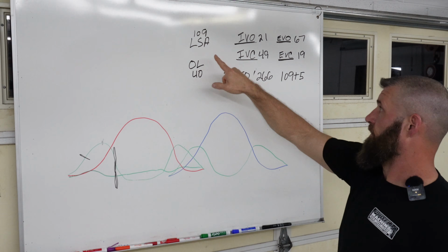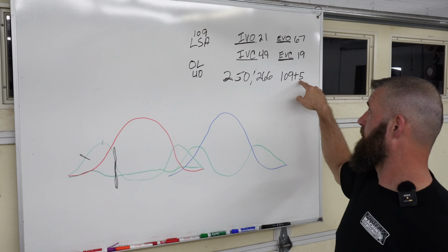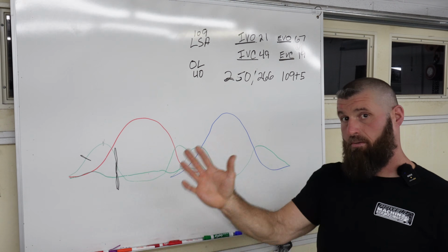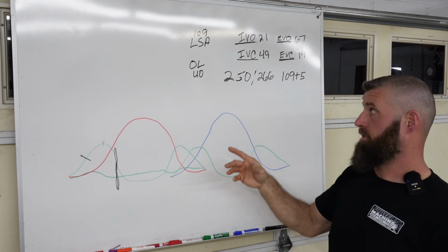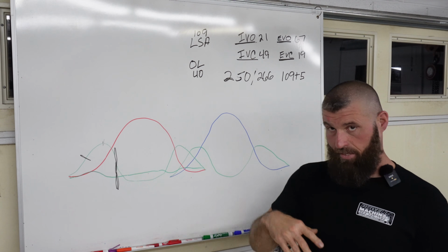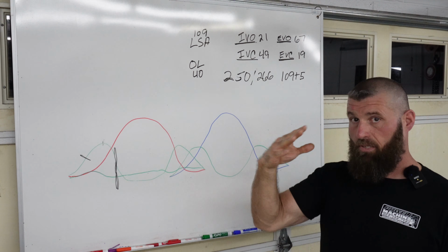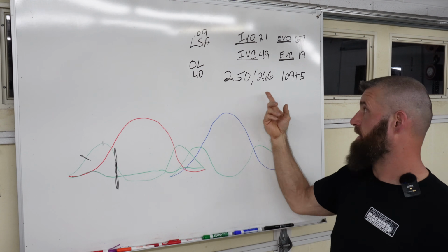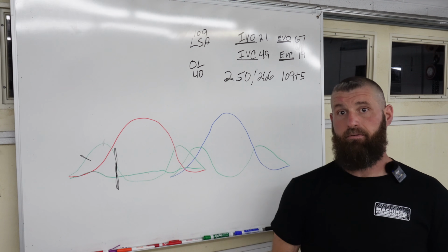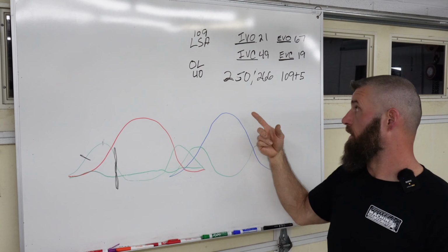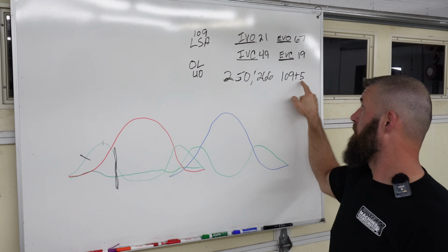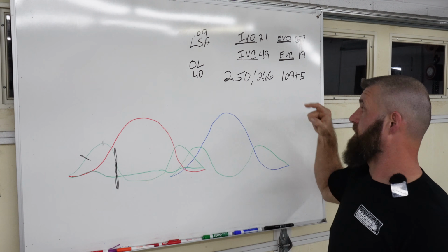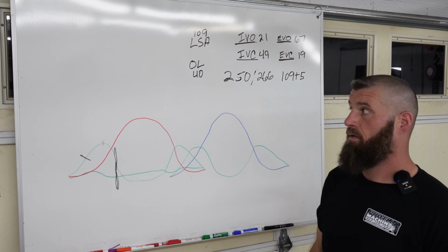Because this number without the intake center line is almost useless. You can move the intake center line, obviously, but if we want the intake center line to be at X, then we need to know where the exhaust center line is to come up with this number so I can grind it, right? So that's why, if you minus this number from this number, that's the intake center line. If you add this number to this number, that's the exhaust center line.